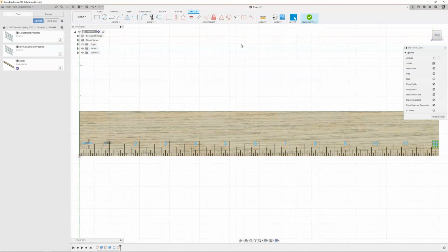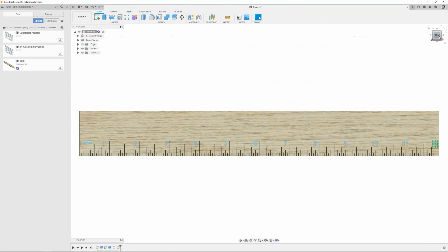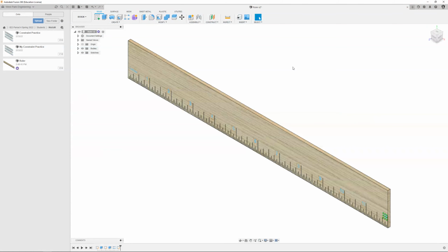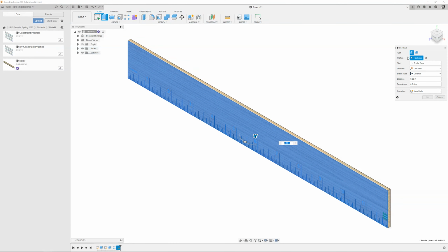Okay. So remember though, right now, this is just a sketch. It's 2-dimensional. It's not 3D. Got to extrude it. Okay. So I'm going to hit finish sketch. Now on the keychain project, I had you guys use emboss, and I found on this one the extrude worked better. I'm not sure what the deal is with that, but usually text you can extrude it or emboss it. So I'm going to extrude it this time. So I'm going to hit extrude, and we're going to do the normal type of extrude this time, not the funky one I did last time.